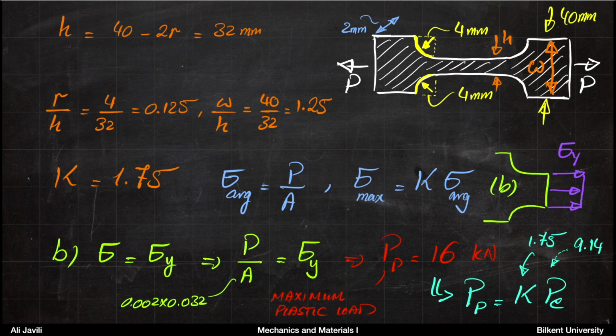And then again, remember we had this nice relation. We said maximum plastic load would be stress concentration factor times maximum elastic load. So you can also check that, and that holds.